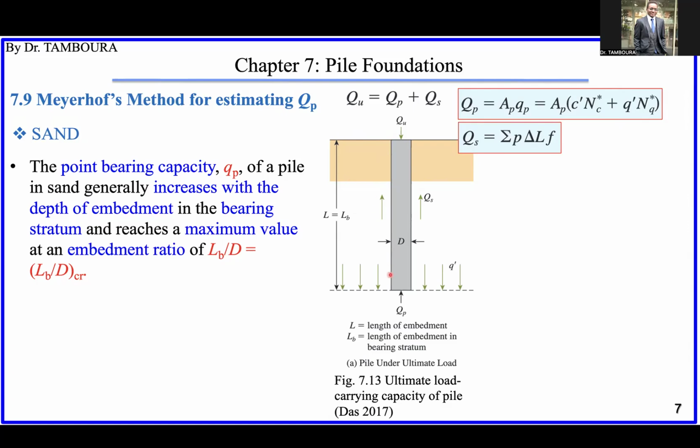But many experiences and studies show that when the embedment increases, the end bearing capacity, the point bearing capacity, will increase until a certain depth is reached.